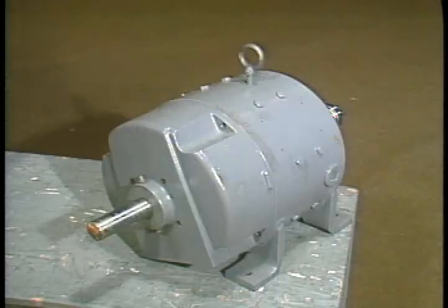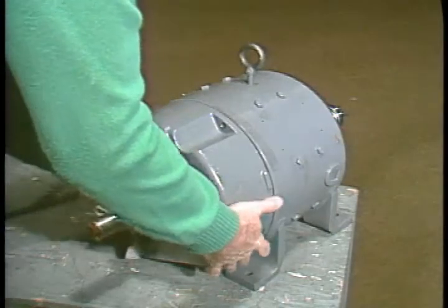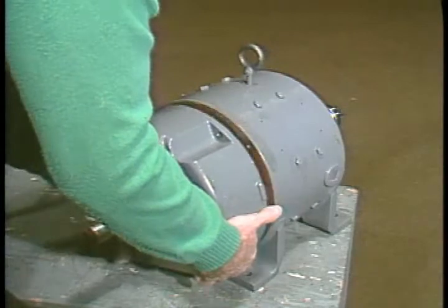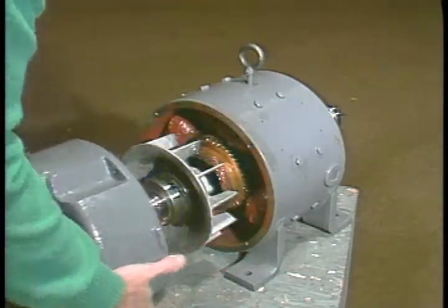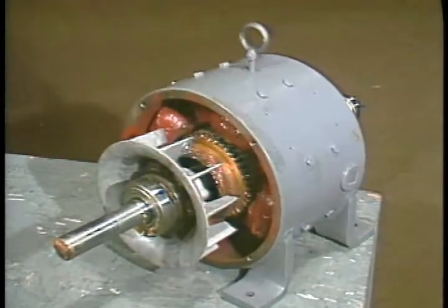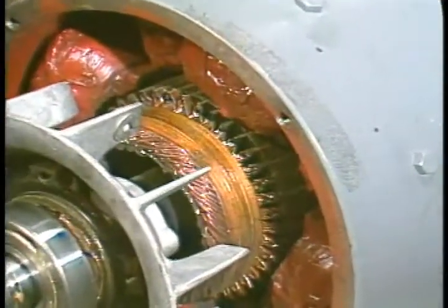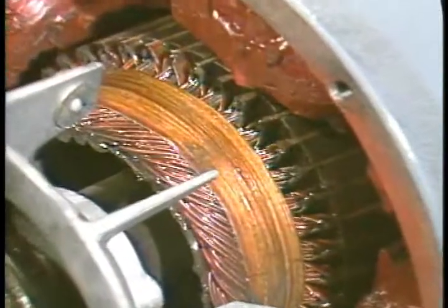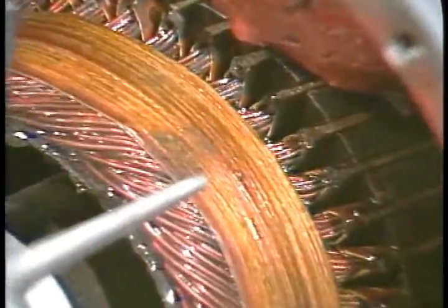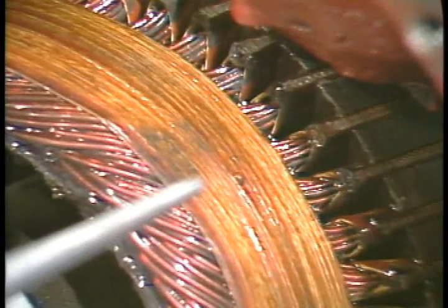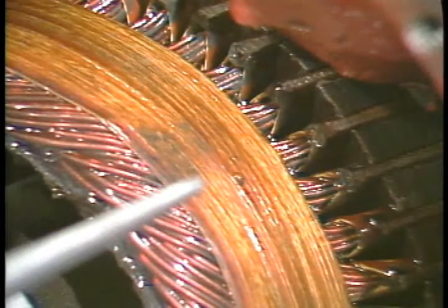Now let's look at how a motor is made and why. Most motors are heavy, and there's a lot of heavy metal, mostly steel and copper, in a motor. The copper in most motors is in the form of wire coils called windings. It conducts the current that creates the magnetic poles. In most motor windings, resistance is kept as low as possible because current flowing through the resistance causes heat. And as we'll see, heat is the main destroyer of motors.